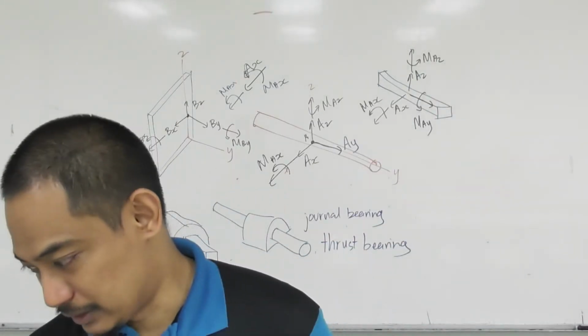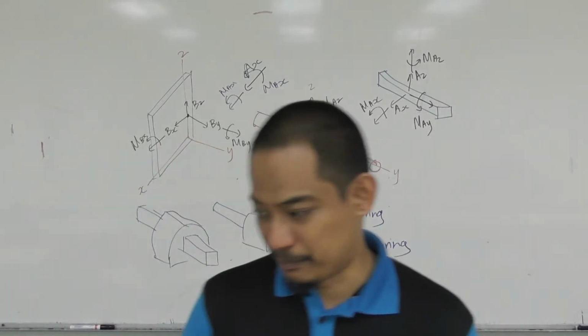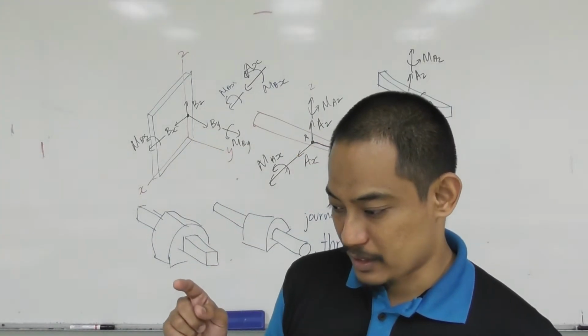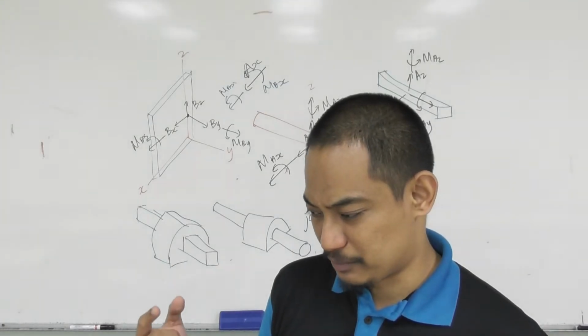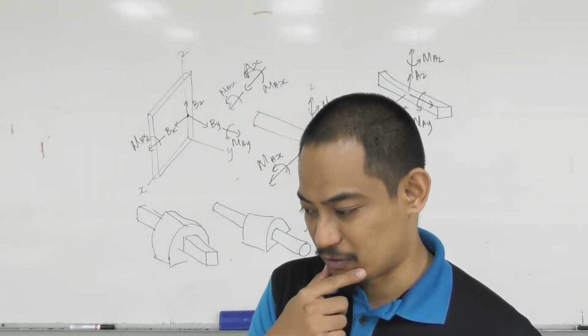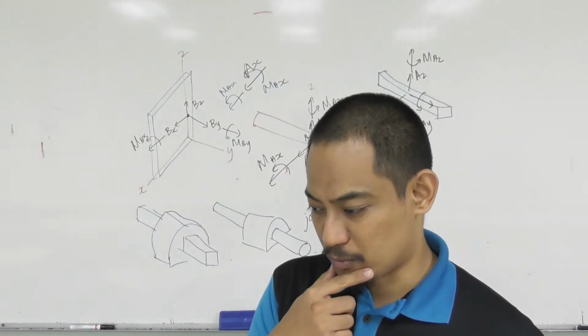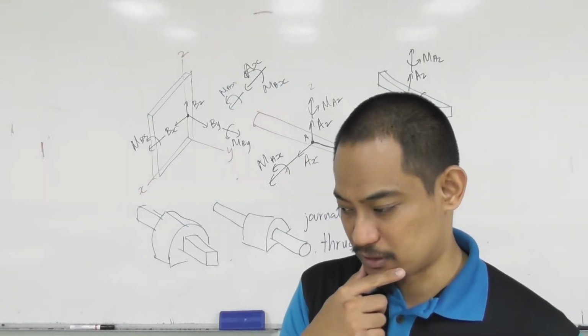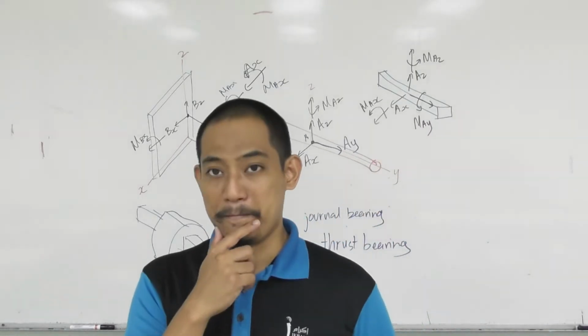So we'll go for some examples, I believe. Alright, an important note before we go to some examples: a single bearing or hinge can prevent rotation by providing a resistive couple moment. However, it's usually preferred to use two or more properly aligned bearings and hinges. In these cases, only force reactions are generated and no moment reactions are created.